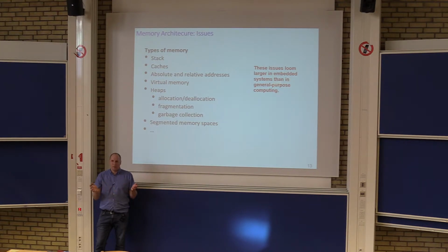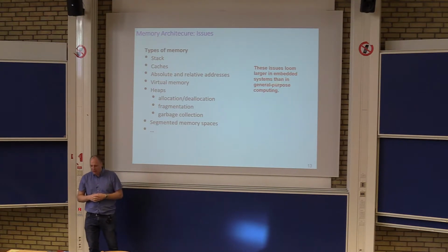But now you will program in C, and in C it's important that you declare the variable. You need to specify, is it an integer, is it a floating point, how many bits will be used, etc. And if you start to make arithmetic computations and you mix integer and floats, strange things can happen. So it's really important that you are aware of these things.